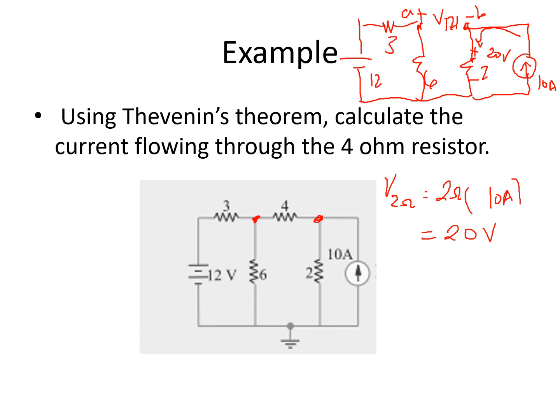Okay, how about in this side? What is the voltage across 6 ohms? So we need the voltage across 6 ohms. So this circuit here is a simple series circuit because this is already open, meaning the current that will be flowing from this source will no longer move at the other part of the circuit because of the open circuit terminal here. So making this a simple series circuit. So if we wanted to solve for the voltage across the 6 ohms, we will just use a simple voltage divider principle.